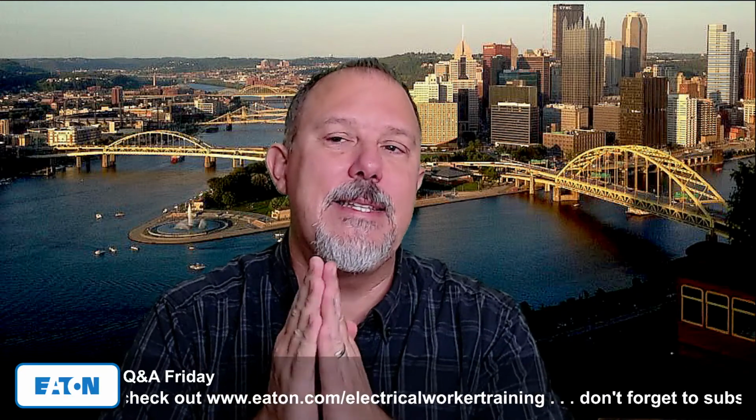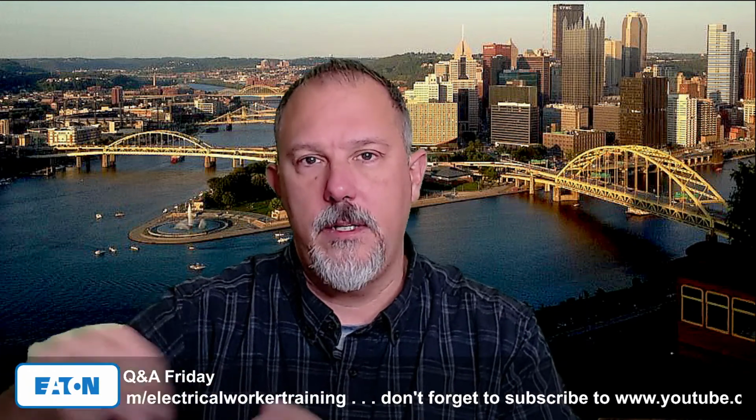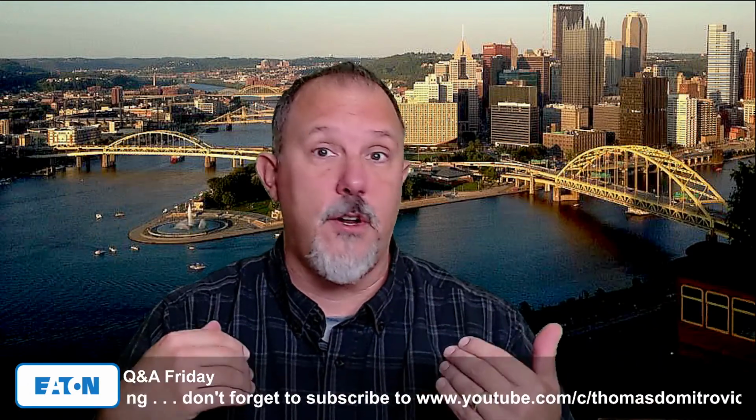Someone had an event where just opening a switchgear door caused an arc flash. And you know what, Robert? That's okay. I've been in those scenarios as well. And that's why I say the more you know and the more intimate you are with your own equipment, and the more qualified you are, the fewer mistakes happen. When you're taking the dead front off, I know I've been there, and you guys have probably been there too, where you take the last screw off, you put your pressure on the door, you take the last bolt out, especially when you're by yourself, and then you got to hold it and pull it off.